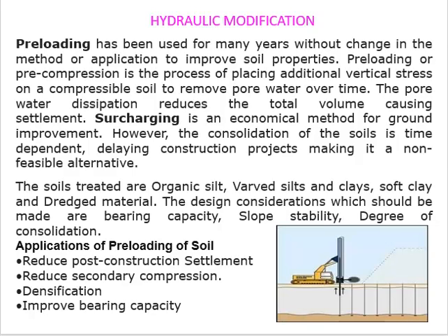In this process, a heavy load is placed on the ground, which is called surcharge. The heavy load is nothing but either soil or stones placed on the ground, which will act as a static pressure and accelerates the process of consolidation. Even the artificial pond created with geomembranes can be used as static load to accelerate the process of expulsion of water from the soil.